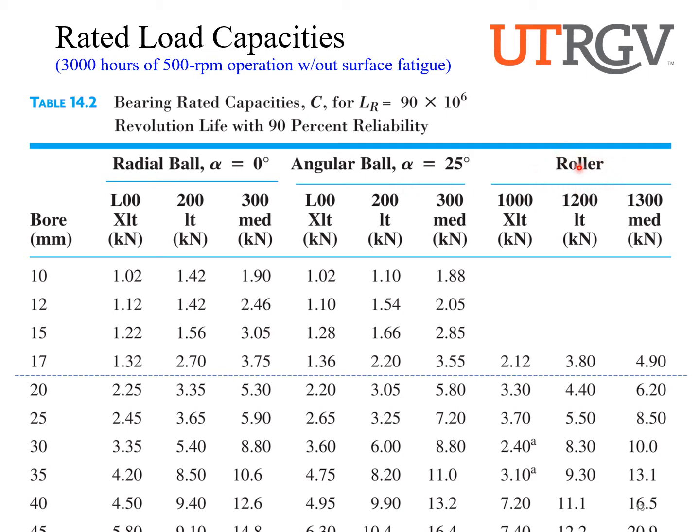We have those cylinders. So I didn't ask you before, but why do you think we have ball and roller bearings? Well, what's different between the two is one is a sphere and one is a cylinder. Remember your equations for contact stresses, right? When you have a ball bearing, you have a point load. So the contact pressures or stresses are always going to be higher for a ball bearing than a roller bearing, because the roller can distribute those stresses over some line or rectangular cross-sectional area.